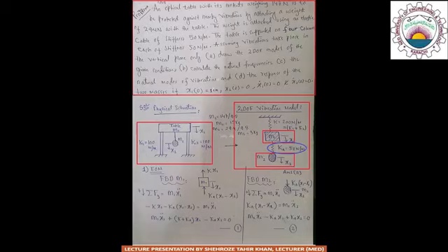So the formulation of equations of motion starts with the individual consideration of each mass one by one. For mass m1, the free body diagram shows that the mass m1 is compressing the stiffness element k, and at the same time it is stretching the stiffness element Ka, which is in this case the elastic cable. Or in other words, the mass m1 is oscillating between the two nodes x1 and x2.